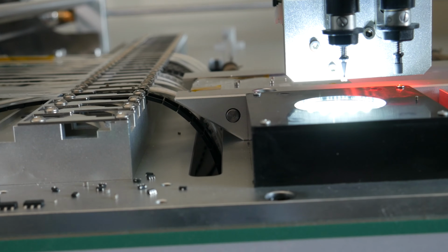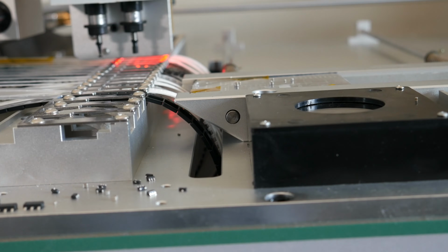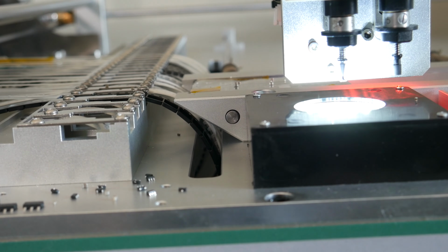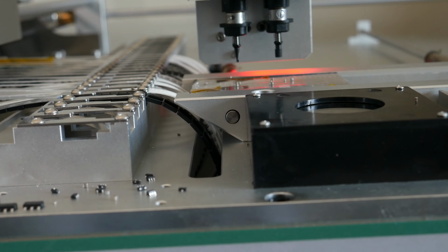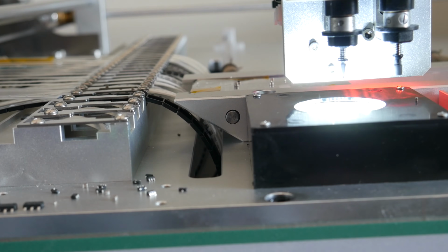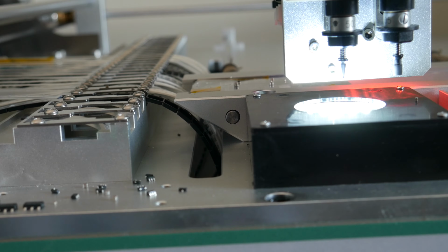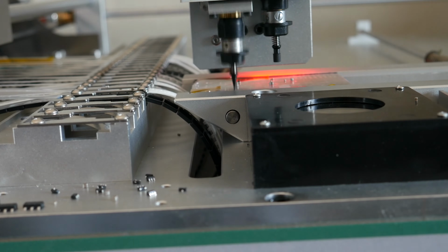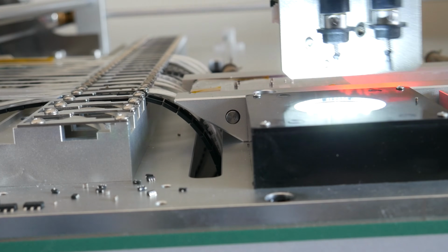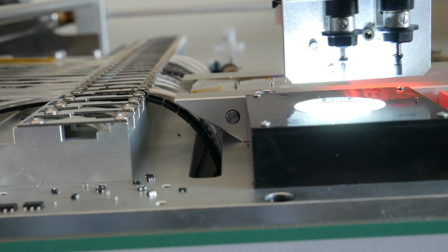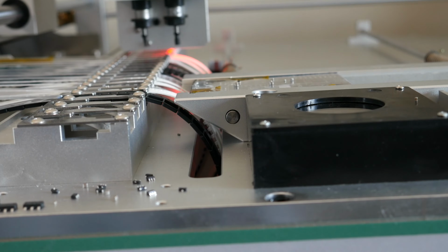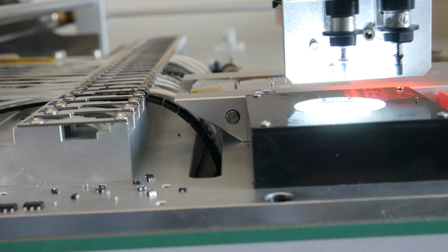There are multiple vision settings. This is running accurate. So the reason why it's dwelling over the camera so long is because it's sitting there trying to figure out where exactly to place each part, and it's compensating for each little minute difference of angle and position, which is not necessarily ideal. Most of the time, you'd probably want to use the fast configuration, simply because it's, well, faster.